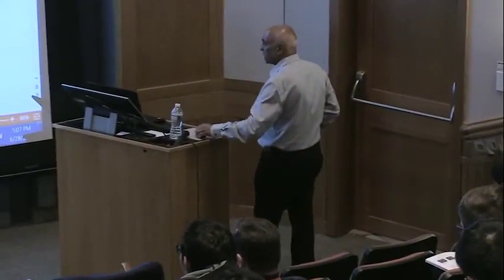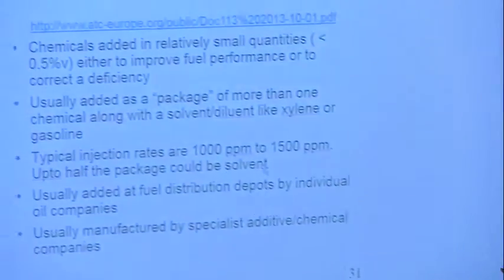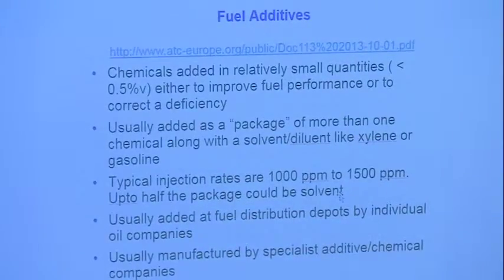So now we come to fuel additives. Incidentally, if anybody is interested in fuel additives, this is an excellent source. This is from the Association of Additive Manufacturers, basically. This is a very good source of information about additives. What are fuel additives? They are chemicals added in relatively small quantities. It's generally accepted that it should be less than 0.5%. I would say 0.2%, basically, to be an additive. Anything more than that is not an additive, it is a fuel component, essentially.